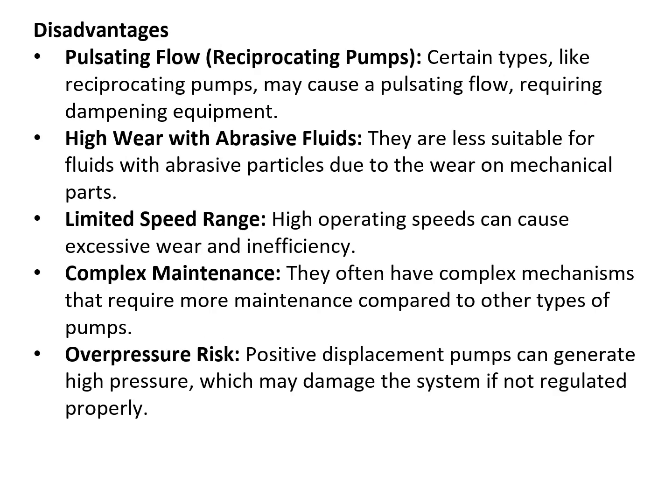The disadvantages: the pulsating flow. Sometimes it may vary if there is any cavitation, and the flow will not be constant throughout the operation. There is also high wear with abrasive fluids. If the fluid has very high density or viscosity, it would affect the efficiency of the motor. There is also a limited speed range, complex maintenance, and overpressure risk. Since it operates continuously with high efficiency and needs to give a constant flow rate, it requires high maintenance. Okay, so these are some of the disadvantages.